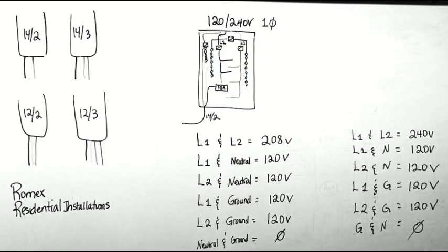Now, what happens to amperage in a series circuit? It stays the same, right? Yes. Now, the rule for the amperage in a parallel circuit is that amps add up. So, in a parallel circuit, the amperage adds up. Now, we do have a constant value in a parallel circuit. Our constant value is going to be voltage.